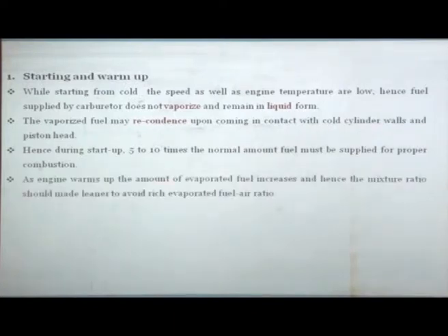As the engine warms up, the amount of evaporated fuel increases, and the fuel-air mixture should be made leaner in order to avoid a rich evaporated fuel-air mixture. So, once the engine starts, because of conduction, convection, radiation, everything will warm up, and you have to avoid the rich evaporated fuel-air ratios. You have to bring it as quickly as possible to the stoichiometric or lean side.